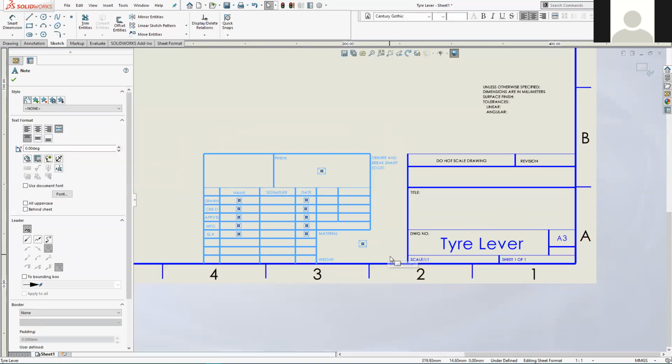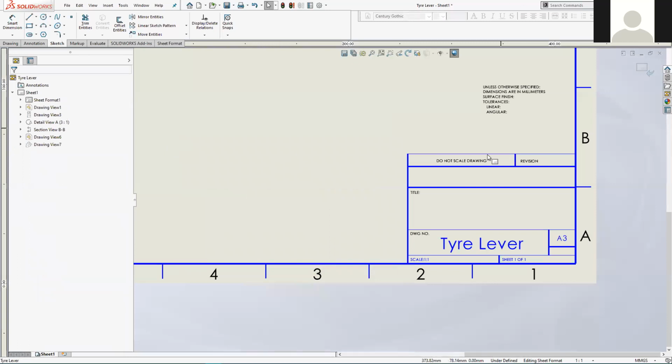And later on, we'll do a bottom right to top left, and that's the opposite behavior, as in anything that's even partially inside the box gets selected, as well as everything that's fully inside. So top left to bottom right, or bottom right to top left, they both have different behavior, certainly in SolidWorks, and I think other things like Word and Publisher behave the same. So when we've got all the things selected that we want to delete, just hit the delete key.